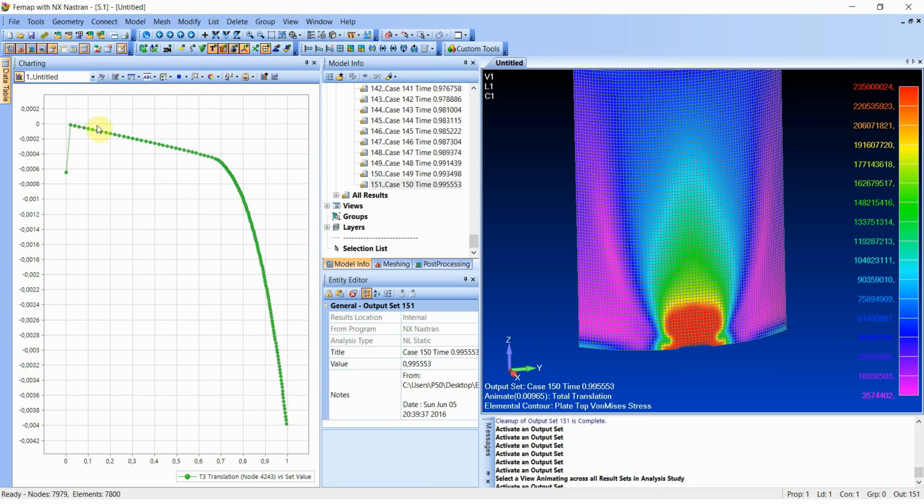If you wish to use this chart in Excel sheet, you can go here and copy chart values and simply paste them into your spreadsheet in Excel and create a chart of your own. It will simply work. Just remember that this is not the load, it is only a multiplier of the load applied, so in this case multiplier of 50 kilonewtons per meter.